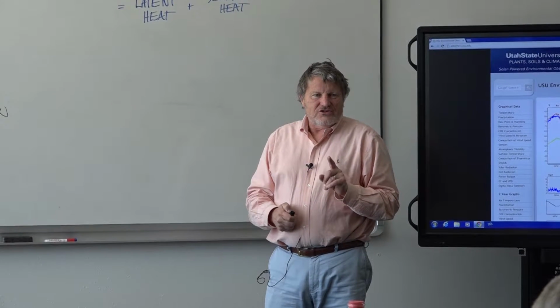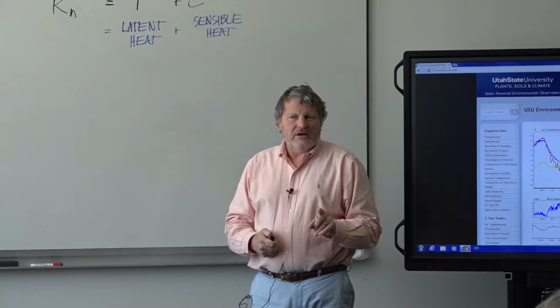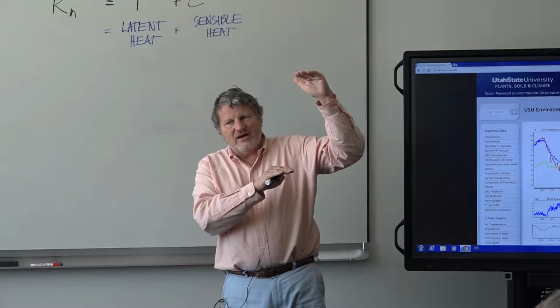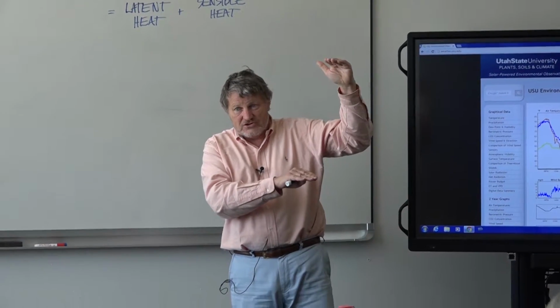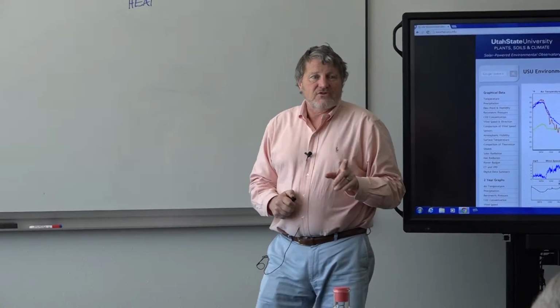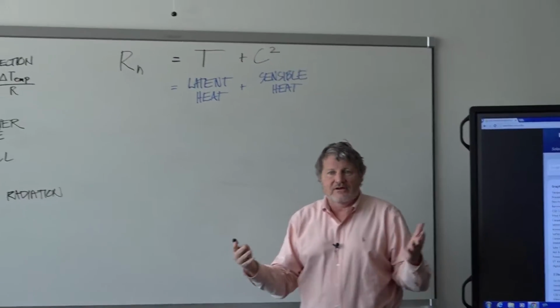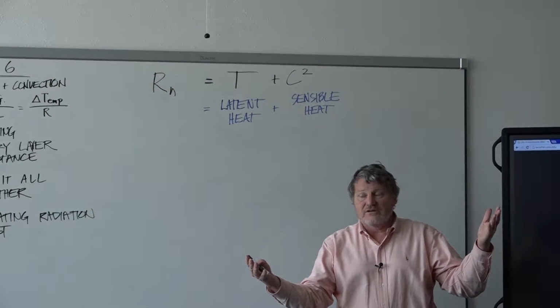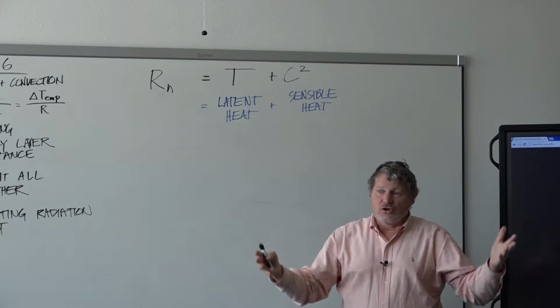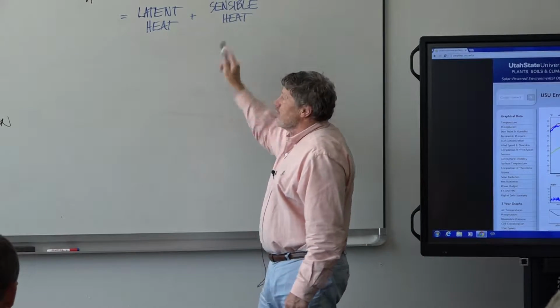Remember, in the case of the psychrometric chart, we spent a lot of time talking about how to calculate the driving gradient, the leaf-to-air vapor pressure difference. That requires some calculations. In the case of conduction and convection, however, this is real simple because the numerator is just the delta T, the delta temperature between the object and the air. So if you know air temperature and you know the surface temperature, both of which we measure, we know the numerator for sensible heat.